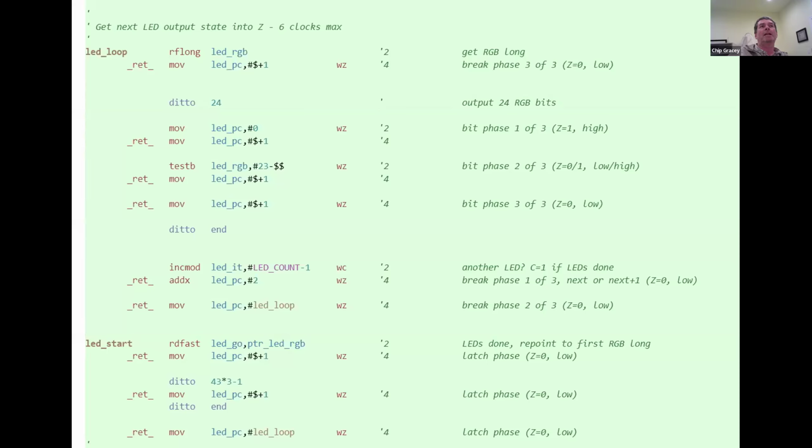But if you get a big ESD event, you want to quash it without just relying on your little surface mount components to handle it all. One thing that we use sometimes is actual spark gaps. They're maybe 10 millimeter long by 8 millimeter diameter, and you can mount them on a circuit board, but they can take tens of kilovolts and many amps.